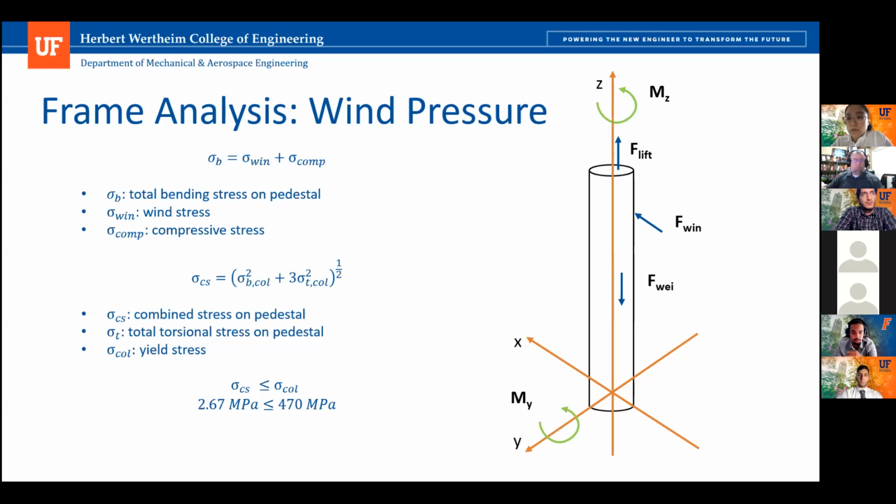Did you do a deflection analysis here? Yes. This would be the deflection of that beam. Does it include deflection of the system above the post? Because this looks like a post, which is pretty robust, but I'm concerned about the rest of your system. No, actually, I don't believe so. That'll be something we'd have to reconsider and calculate.